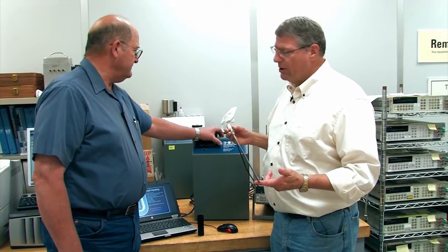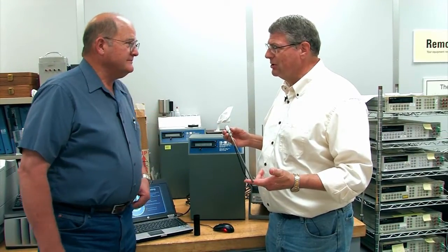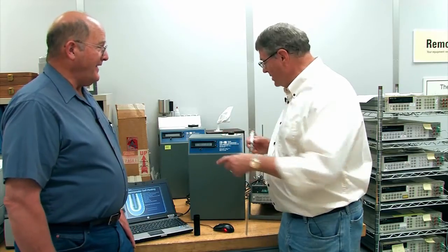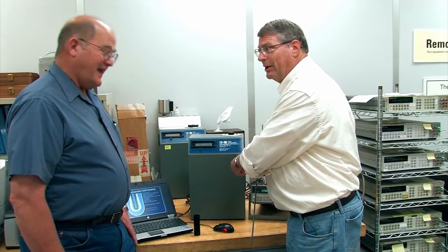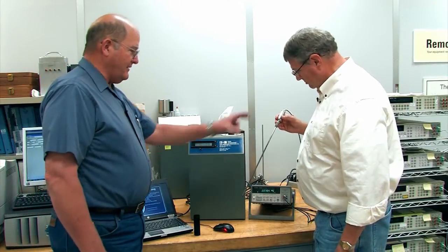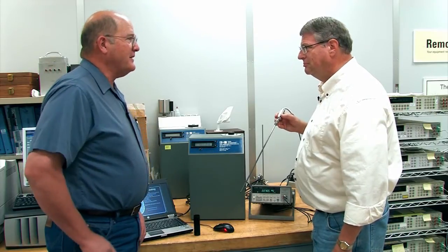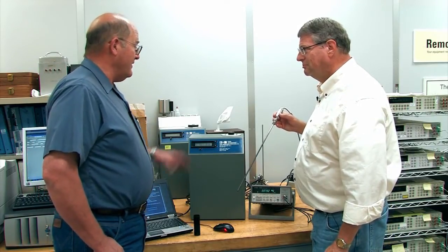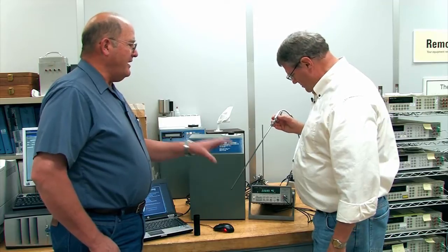We also haven't calibrated this in quite a while, so it'll be interesting to see how close to real we are. I don't doubt that you are truly at 0.01. And the uncertainty on this instrument is approximately half a millikelvin. The uncertainty on that instrument, the combination of the two, is somewhere between 5 and 7 millikelvin. So you've got a good ratio between the standard and the unit being tested.